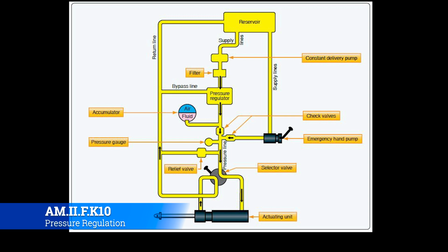However, typically relief valves are not going to be customizable. You're not going to be able to adjust it up and down. It's just there as a safety, much like the hydraulic fuse worked as a tourniquet. This simply works like an open door. If there's too much pressure inside the system, that opens the door and lets some, if not all, of the pressure out. Usually, it's just enough to let off that pressure, and then it'll reseat once the pressure drops, because it's going to have a little ball check valve or a little ball valve with a spring on it. That's how that works. But that's your pressure regulation devices.